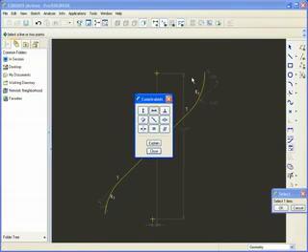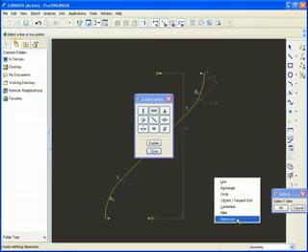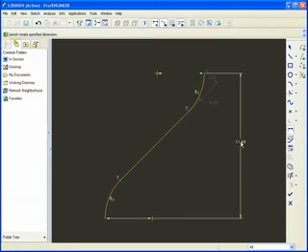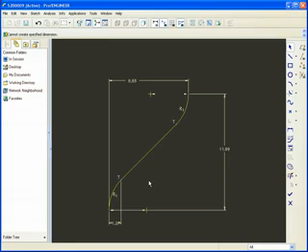Just to make the sketch happen a little easier, I'm going to call these horizontal like so, and then add some dimensions for the height, which you can call perhaps the Y direction, and then the width, which will be the X direction. And I'm going to take it one step further. I'm going to actually control the X value for this, and that's going to give me a control of how this will, or where the pitch will change.